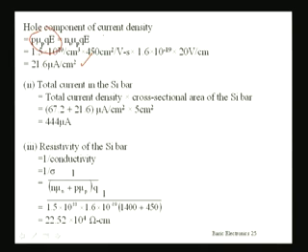So current density in microampere per cm square we have found out. Each of this hole component and electron component you have to add up. Then you will be getting the total current density. So 67.2 and 21.6, this is the total current density, multiply it by the cross-sectional area 5 centimeter square. So finally we get 444 microampere, the current flowing in the silicon bar.